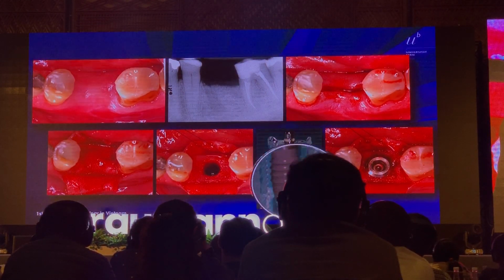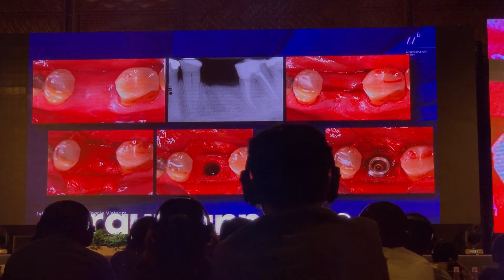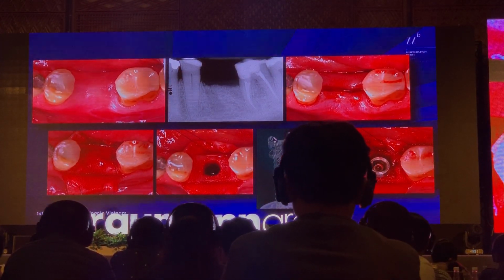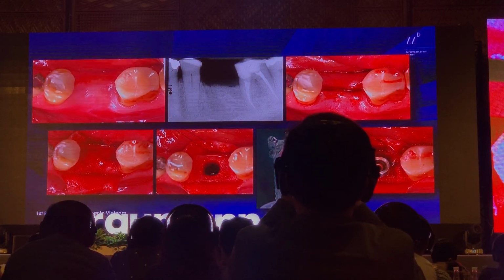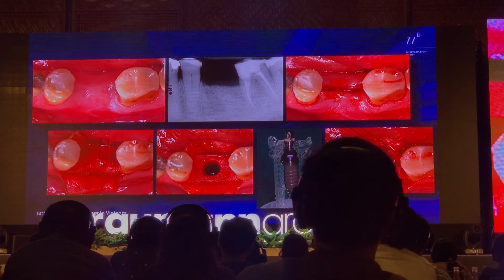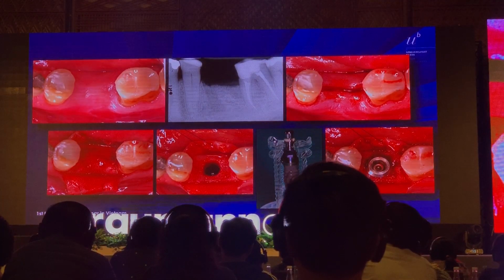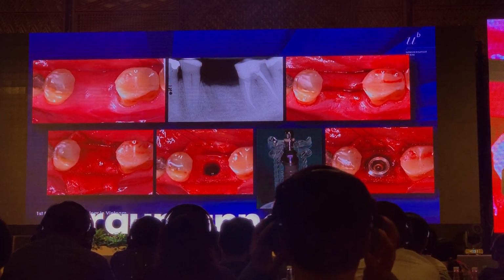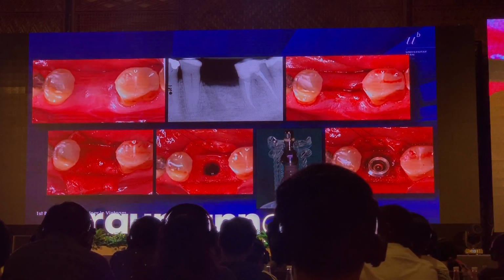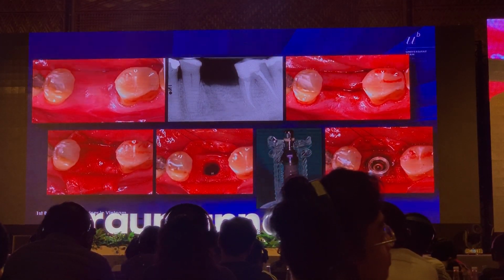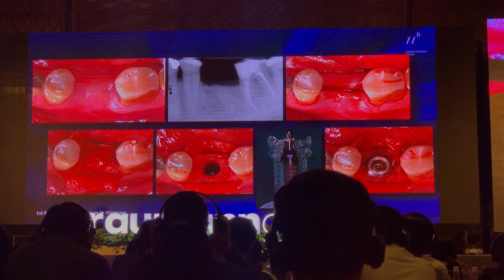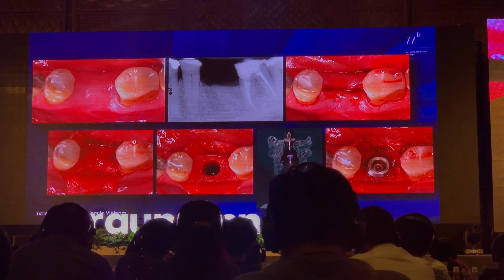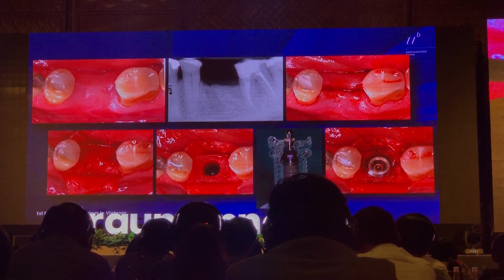That means Straumann, when they produce these implants and they get this surface, it is a sandblasting process and an etching process with an acid etching. So the sandblasting produces the roughness like this, and then the acid etching these small pits, the small characterization. When you take that out of this treatment, then of course you have to rinse it with lots of sterile water, to get rid of the acid from the surface. And then of course you have a hydrophilic surface.